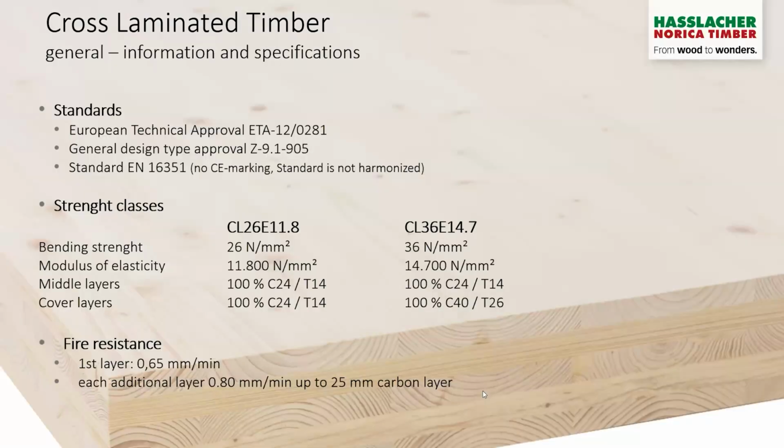Cross-laminated timber is made up of crosswise oriented glued wooden lamellas. So far, however, there has been a failure to harmonize the applicable regulations and standards, which means that it is still necessary to have company-specific structures and specifications certified. However, it is clear that the building material is a high-performance material with precisely defined characteristic values and properties. This makes it clear that the behavior in the installed state can be precisely predetermined, whether in terms of mechanical load-bearing capacity, moisture resistance, or fire resistance.